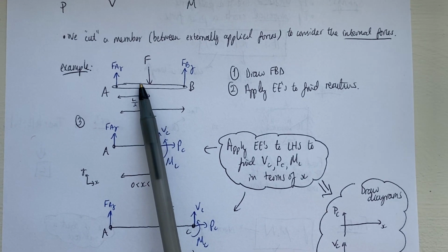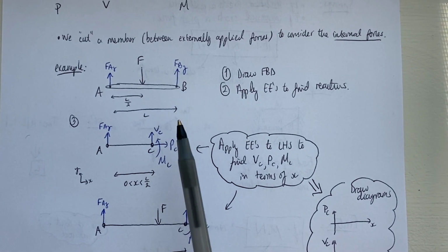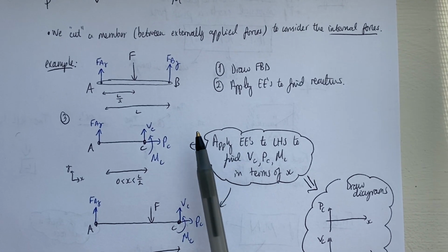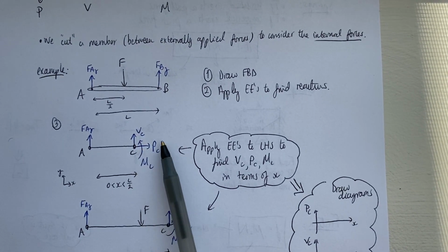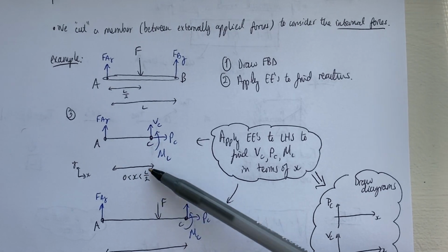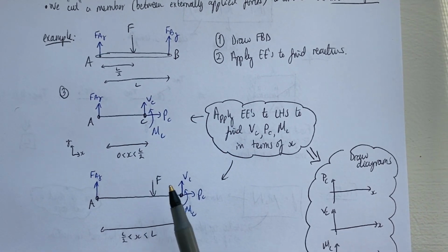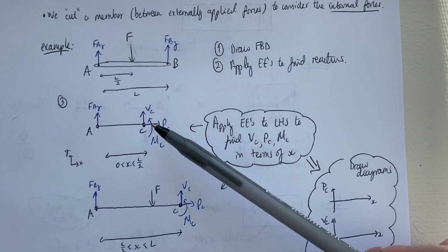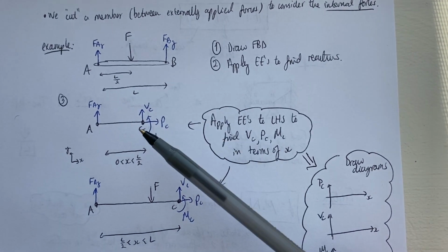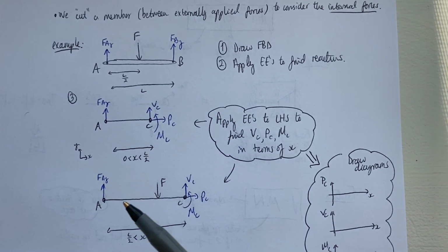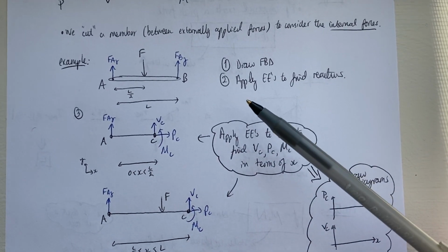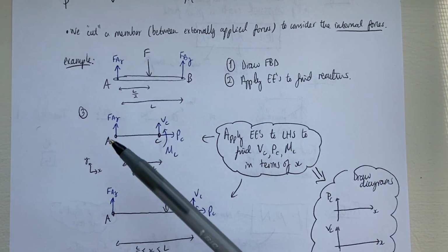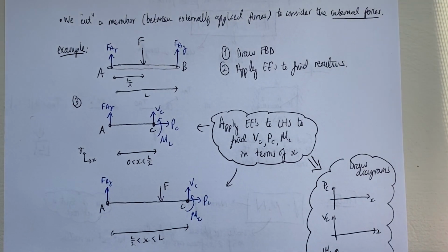Remember, if I've cut it, then there's a corresponding right hand side of the free body diagram which I've chosen not to draw, but they will have the opposing directions, right, because they need to be equal and opposite. I've just chosen to draw the left hand side because I only have 3 unknowns on the left hand side in both cases, assuming that I know the reaction at A, given that I've applied the equilibrium equations and done all of this preamble first.